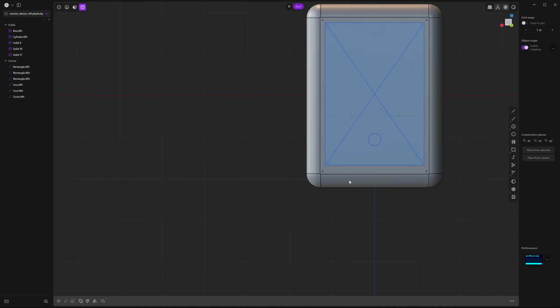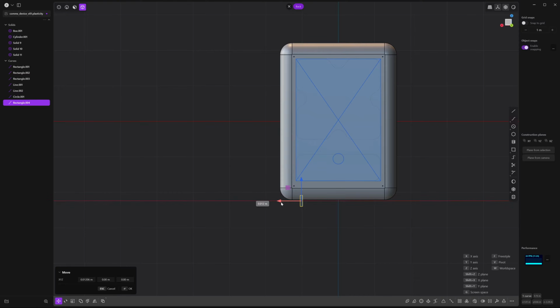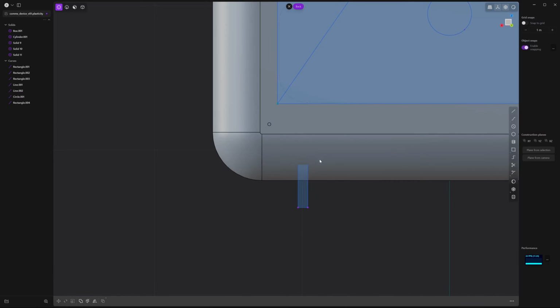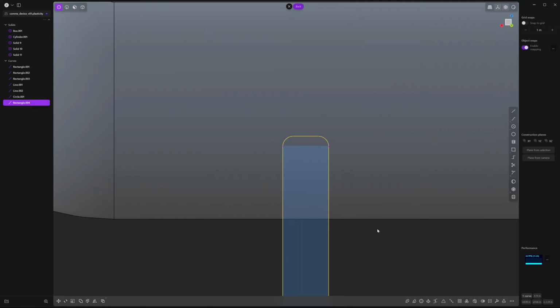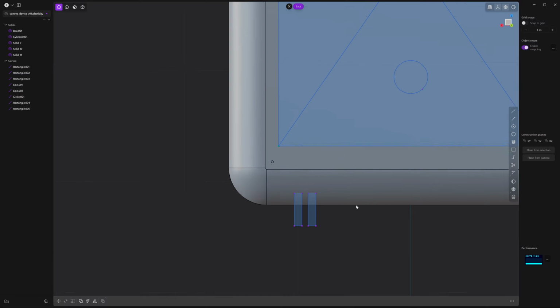I do want a little bit of an opening down here. So let's go ahead and create one rectangle. That's pretty thin. Move it over around here. Next, press 1 to go to point mode. Select these top 2 points. Press B and D. And if this handle is moving a little bit too abruptly, maybe you should hold the shift so you can have smaller increments in that shift. And just round it out a little bit with that fillet. Press Shift G and we're going to duplicate that towards the x-axis on the right. I'm just going to cut right through this shape later on.